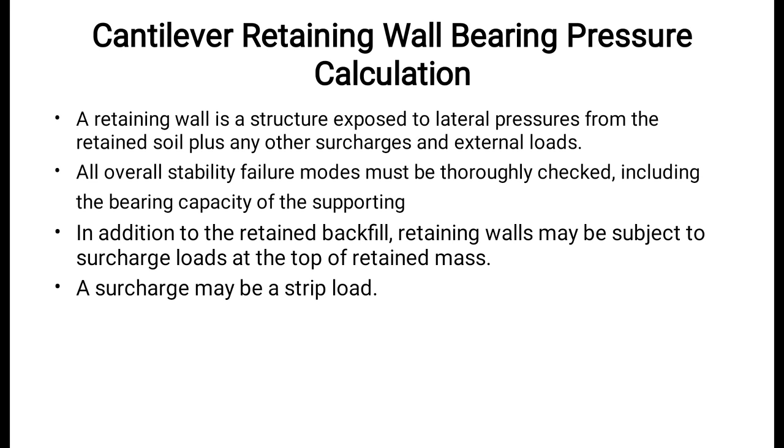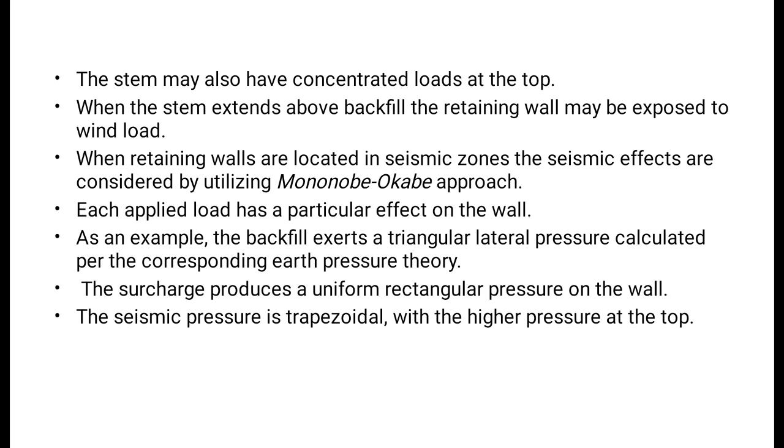In addition to the retained backfill, retaining walls may be subject to surcharge loads at the top of the retained mass. A surcharge may be a strip load. The stem may also have concentrated loads at the top. When the stem extends above the backfill, the retaining wall may be exposed to wind load. When retaining walls are located in seismic zones, the seismic effects are also considered.